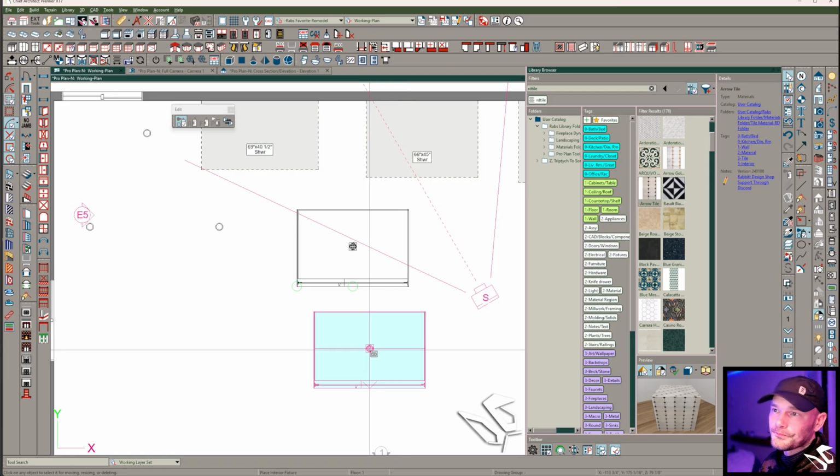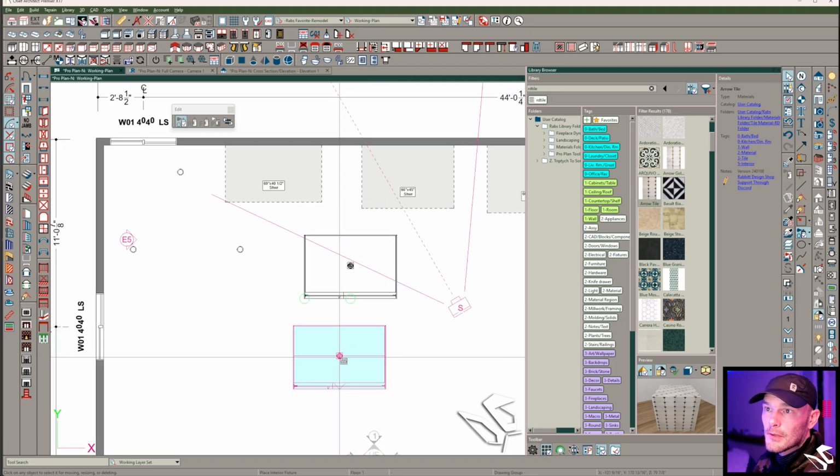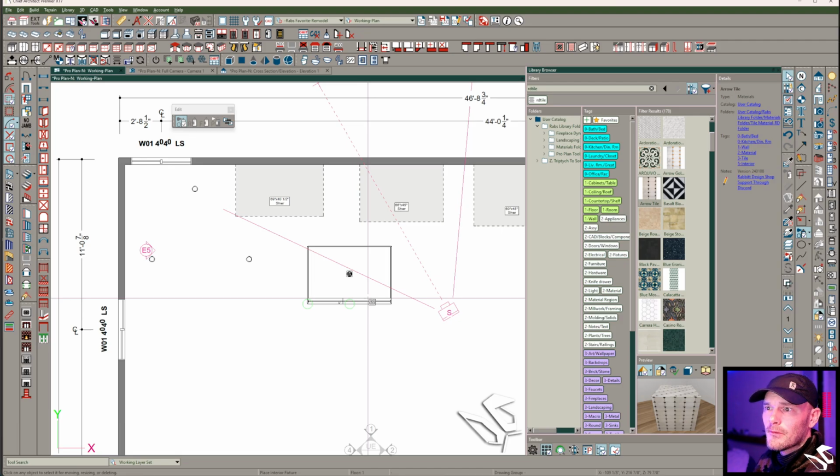Pretty good. The other great part about this is wall elevations just cut through this. We're not generating a room with this. If you want to generate a room, you could. How would you do that? Just use an invisible wall. Simple as that. So, pretty powerful workflow.